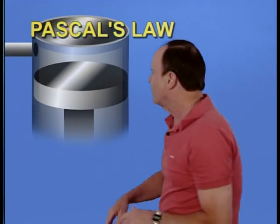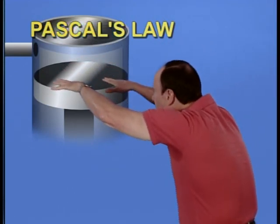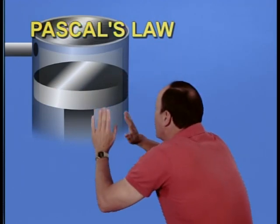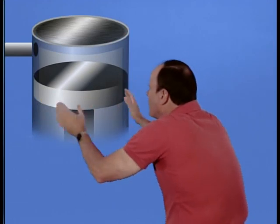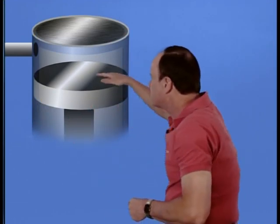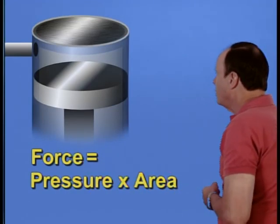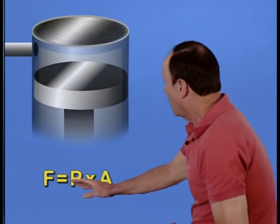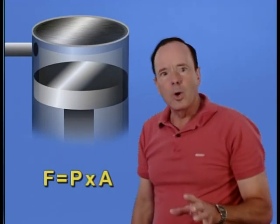It says the force available in a hydraulic system is equal to the pressure in the cylinder multiplied by the cross-sectional area of the piston. So you take the area of the piston and multiply it times the pressure, and that's the force applied on the cylinder. So you can make a formula out of it. You can say that force equals pressure times area, and you can abbreviate it a little bit by saying F equals P times A.